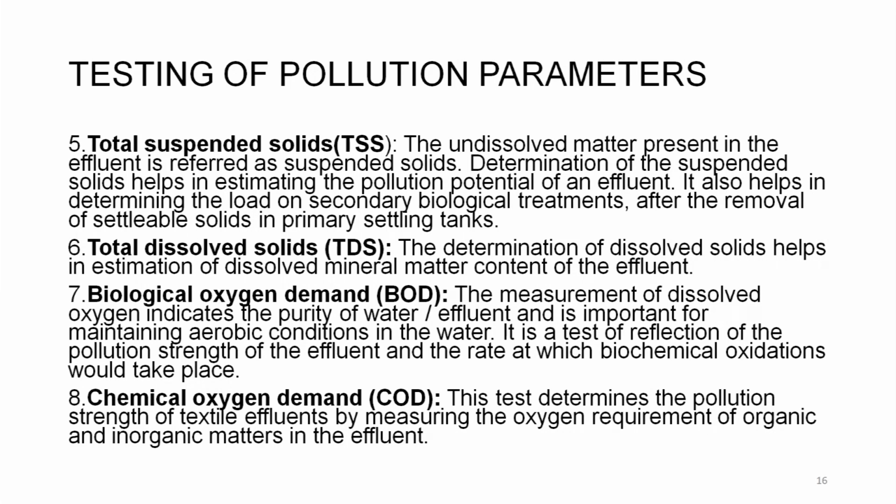It is a test reflecting the pollution strength of the effluent and the rate at which the biochemical oxidation would take place. So, it is indicative of how much dissolved oxygen still persists in the effluent. Chemical oxygen demand. This test determines the pollution strength of the textile effluent by measuring the oxygen requirement of organic and inorganic matter in the effluent.